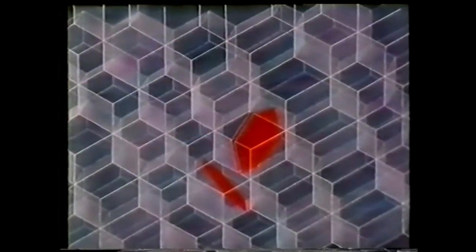A polycrystalline or synthetic diamond differs from a natural diamond because instead of a single crystal, it's got thousands of randomly placed crystals joined together. It's because of this crystal orientation that the problems of cleavage and fracture don't arise. Even if one or two crystals are fractured, it wouldn't affect the overall performance of the tool, as there are thousands remaining which are correctly aligned.